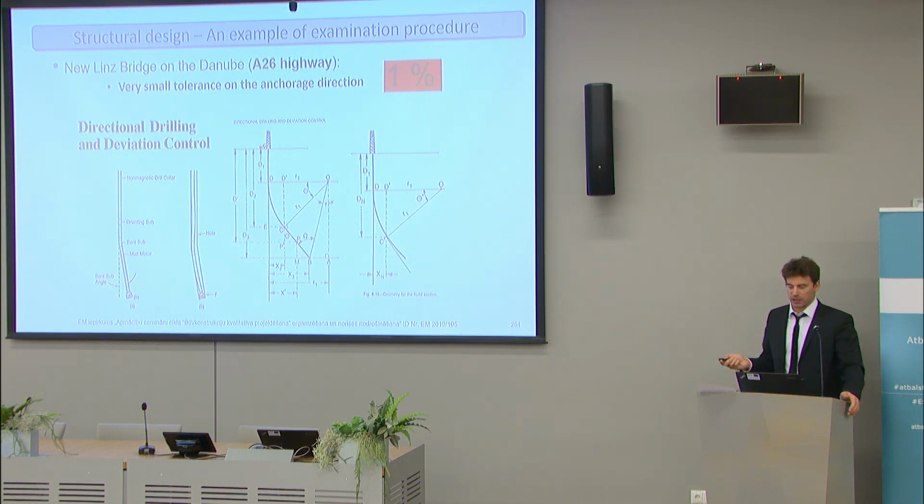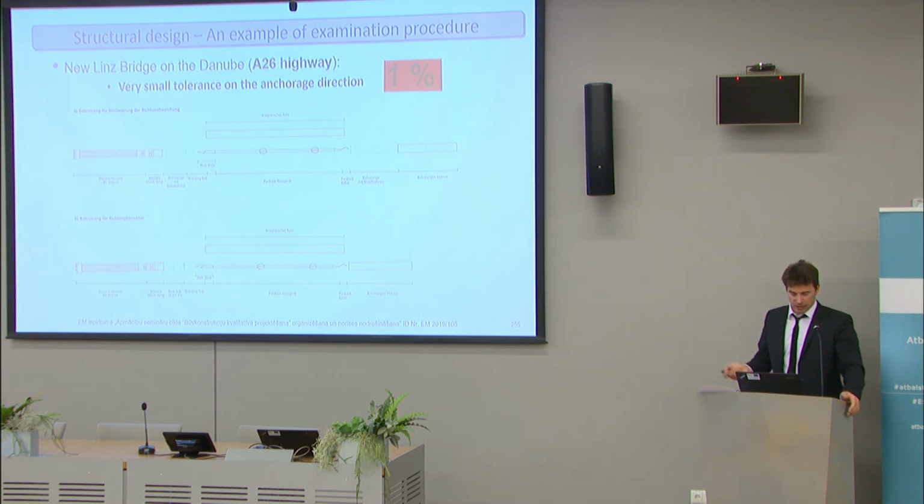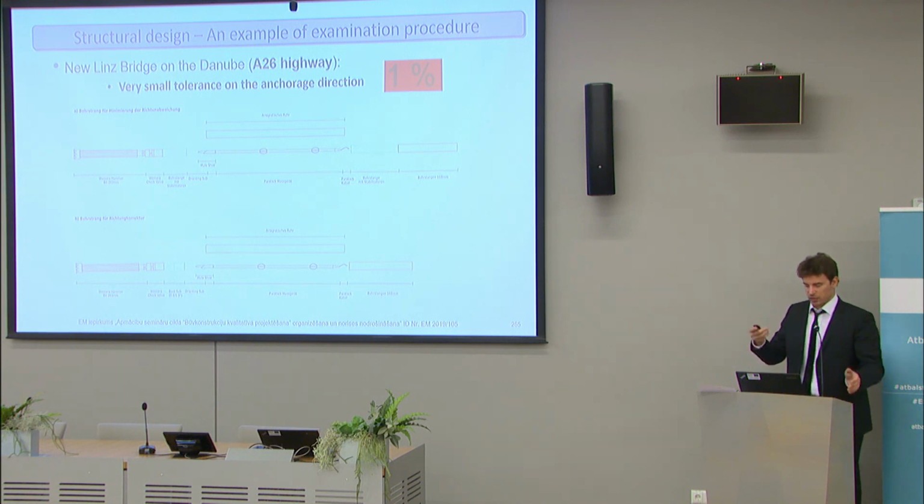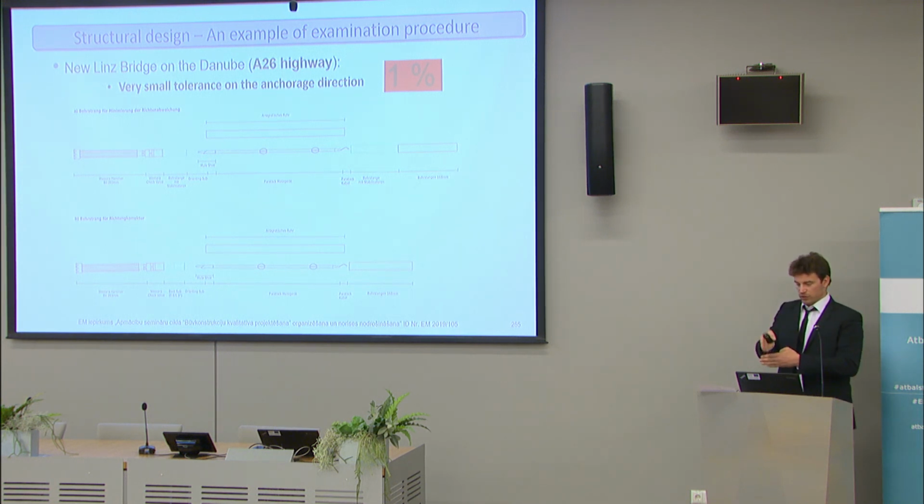Nobody knew if this was working, but with this technology, you see here, this is put inside, this is called paratrack. It has different instruments inside that can measure by means of a magnetic field that you put on the site. It can give you the azimuth, and it can give you the inclination with another instrument, an inclinometer. In this way it gives you the position on this angle and the position on this angle, and you are able to know where you are.